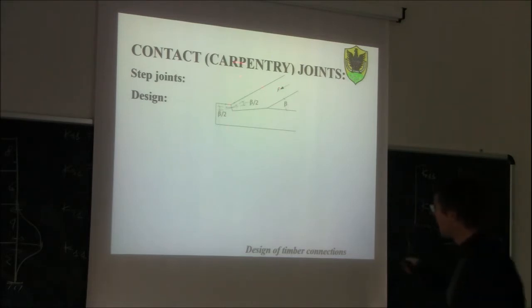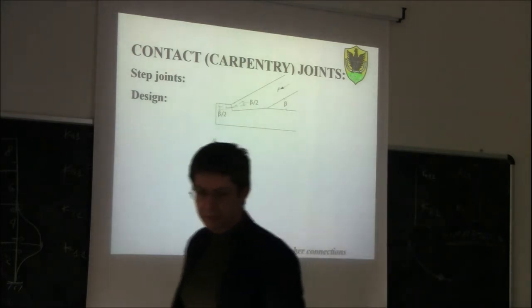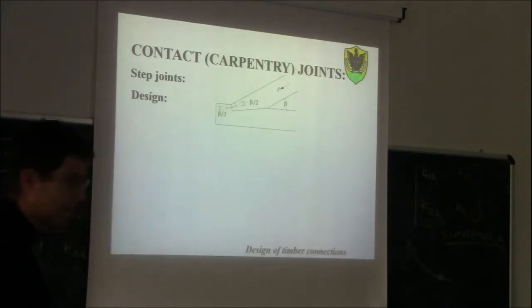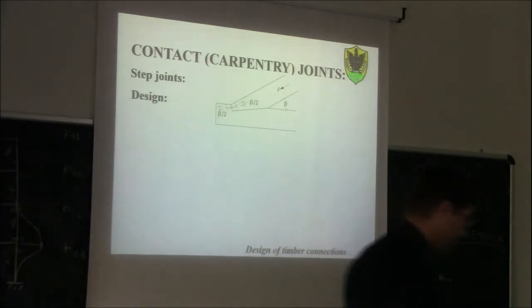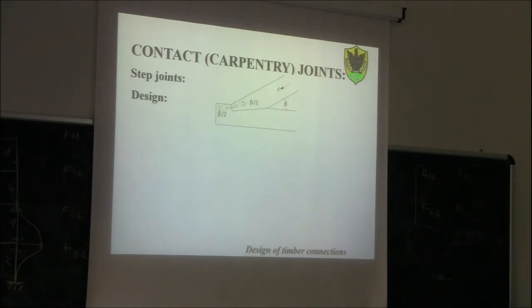Well, we have some plasticization in the joint, but there's also another very tricky, even worse failure mechanism rather than compression perpendicular to the grain. If you remember, compression perpendicular to the grain, in the end, is a plastic deformation. It's very hard to get a real failure. I mean, in the end you get lots of indentation, lots of plastic deformation, but you don't have a real failure. Instead here, you could have a real failure if something happened.